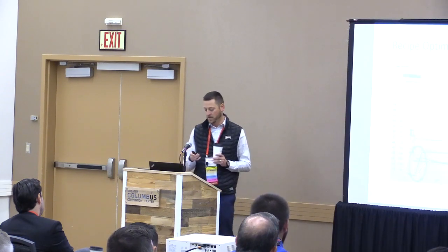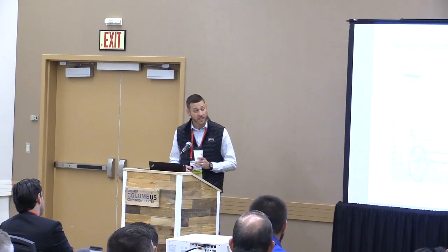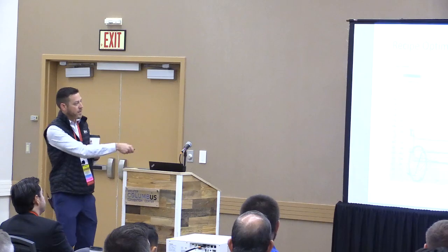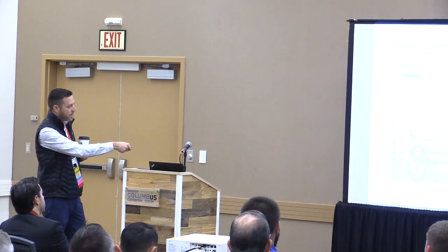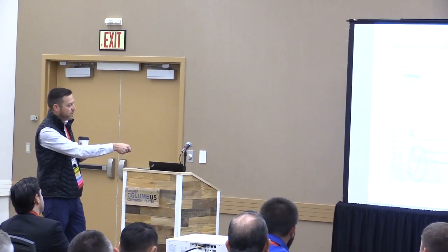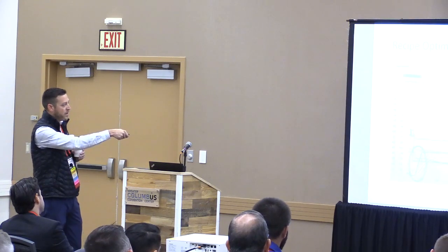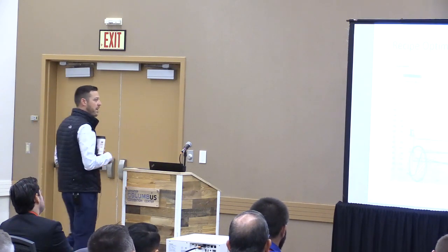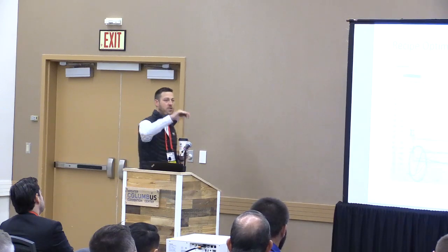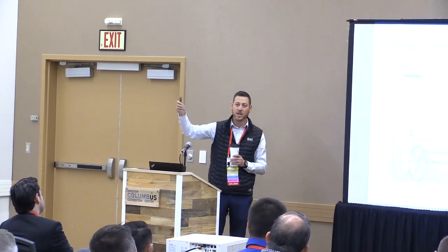The other thing I'll note here, I don't know if this has a laser. It does have a laser, so I'll step around here. So you can kind of see here that there's maybe a bigger discrepancy when it advances between the set point and the actual temperature, and then here it's a little bit tighter. So I'll go over that in a few minutes, but in the recipe you can say how close you want the work thermocouples to be to the set point before it advances to the next segment. And that's what they're doing there.